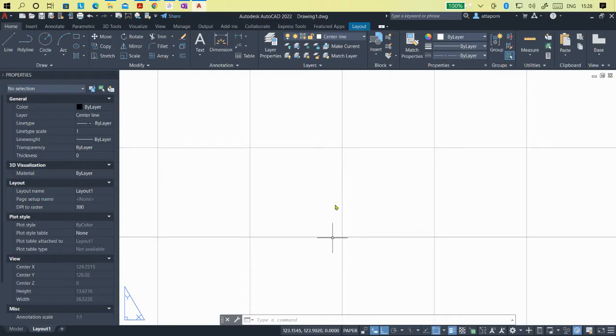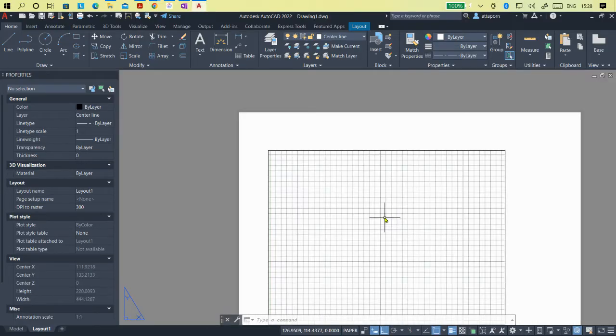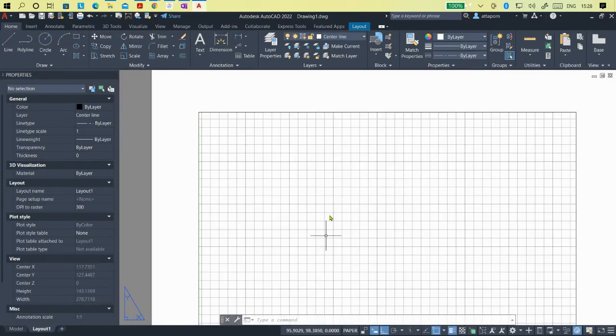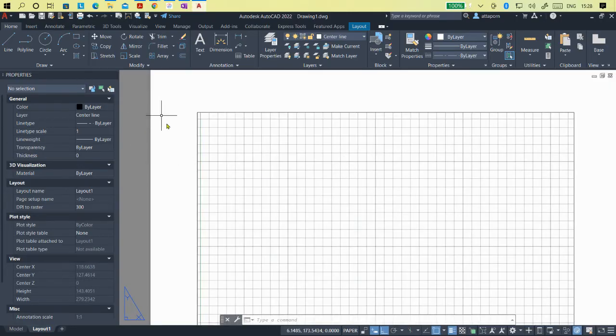If we double click, we cannot come back to the drawing paper layer or the outside layer, okay? The whole layer we cannot see again. Please beware this, okay? Do not double click. When you double click on this model space, please make sure you have an area to double click, maybe outside this window or the clear area, okay?